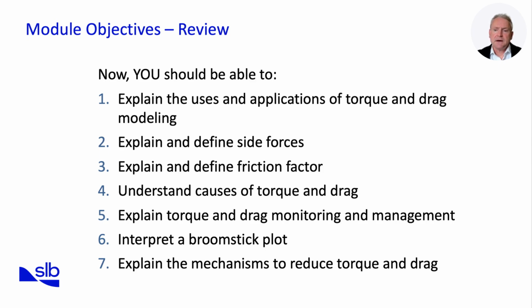The key takeaway was that string components move through multiple sections as the well deepens, so placement must anticipate future conditions. Finally, we reviewed torque and drag reduction strategies, including mechanical tools, mud additives, and operational practices for optimization.